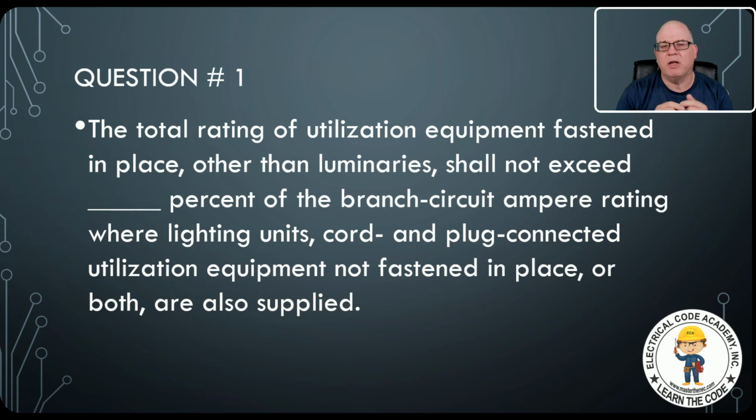But let's answer this question. If you go to the index, you'll probably see branch circuits, and under branch circuits, you'll see something that talks about permissible loads, because that's what we're saying here. We're trying to find out if I've got all these conditions in place on this branch circuit, and I want to put a utilization equipment on it that is fastened in place, but it's part of a circuit that has lighting units and other utilization equipment that is not fastened in place, that is cord and plug connected, what's the maximum size, if you will, of this fastened-in-place utilization equipment I can apply to this branch circuit? That's what we're hunting for. Okay, so again, branch circuit is where you want to go in the index.